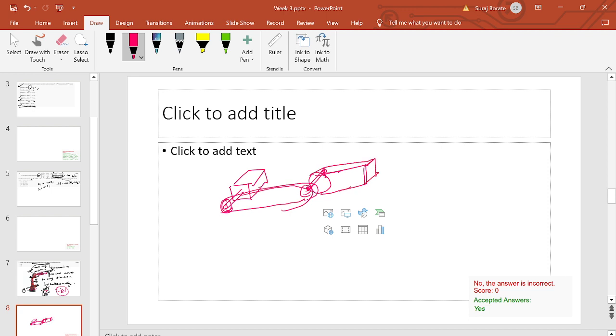Okay, the reason we are not putting a motor directly over here is that we want the motor to be as close to the base. It should not be very far away. And the second thing is we want to have some gear ratio increase over here through a pulley. So there should be a smaller pulley and a bigger pulley over here, so the gear ratio will be more. Something like one and two. If you have any doubts, I will try to clarify about gear ratios and all.